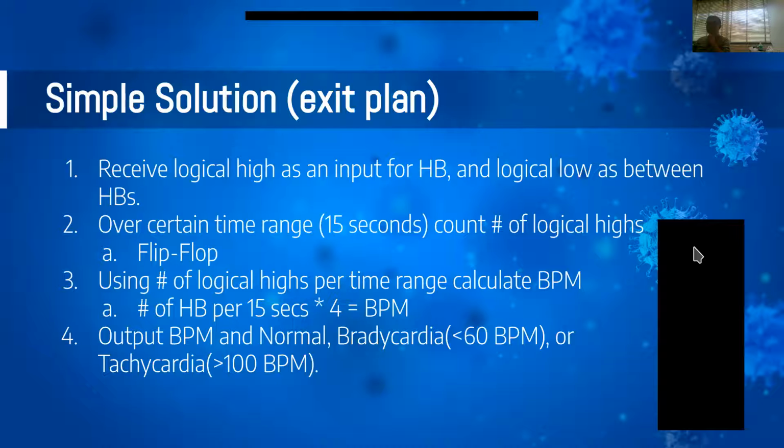and use it to work as a clock. Within 15 seconds, I'll lower that to nanoseconds, but for right now, 15 seconds, and then we count the number of logical highs, which represent the heartbeats, and then you can calculate the beats per minute. So that's maybe my simple solution. That's my first goal.